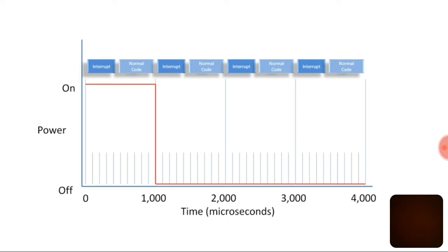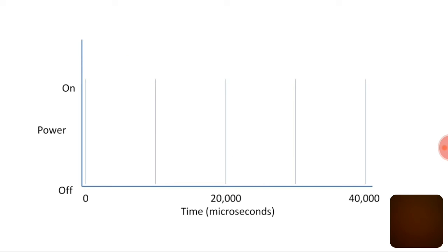In addition, you probably want your microcontroller to be performing tasks other than LED PWM brightness control, so there has to be some spare execution time between interrupts to do all of the other more general processing tasks. With PWM control of LEDs, the primary advantage of higher resolutions is that it results in a smaller difference between brightness levels from the LED.